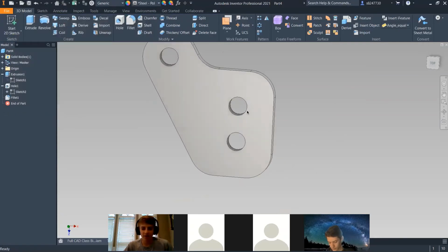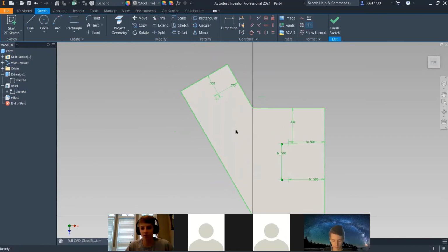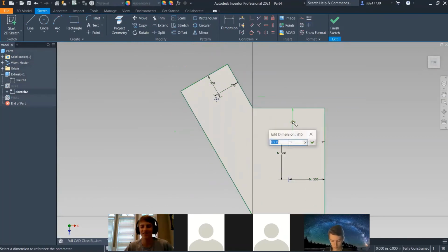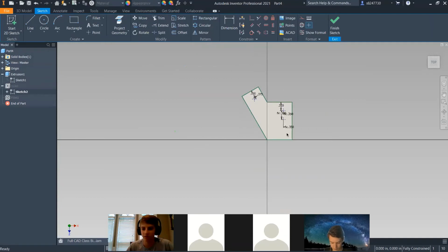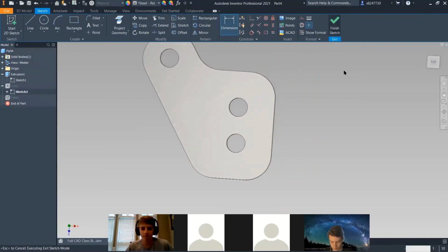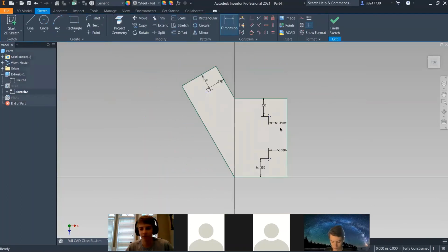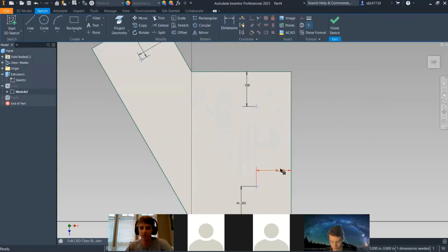As I'm looking at this, these holes look pretty close together, and from experience, it'd be pretty hard to fit a 1/4-20 bolt right there. So I'm going to go back into the hole sketch, and make this 0.35. This, and make this 0.35. Also, there we go. So that's a problem because now, since these are all slaves, one is controlling all the other ones. I still want them to be 0.5, so I have to go in and do the divisions.